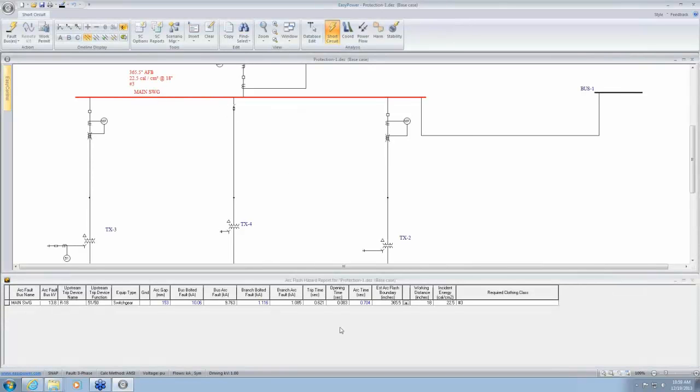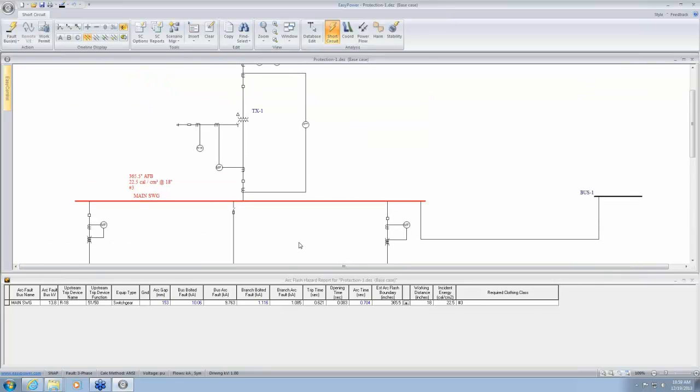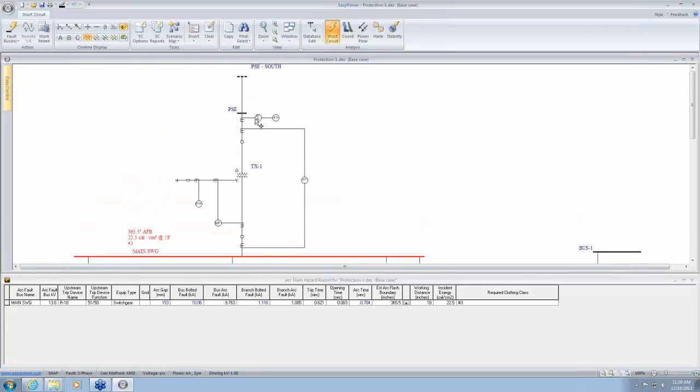Okay, in my spreadsheet, I've got relay trip time. Anytime we have relays as the upstream trip device, what we report in the trip time is the trip time of the relay. So let me show you a TCC plot. R18 is this one.